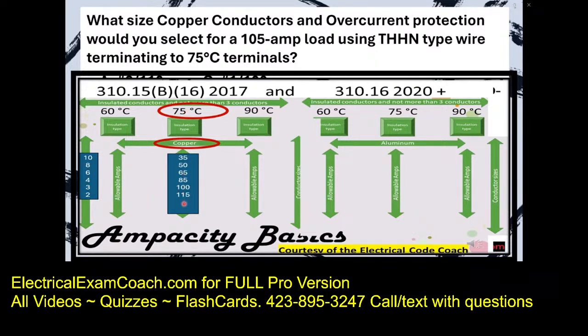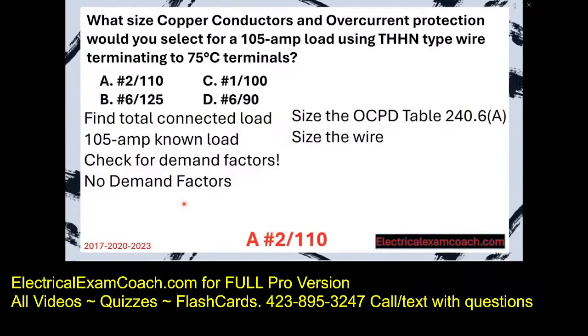And we go down and find a wire that covers the known load, 105 amps, and we're going to end up with a number 2 wire on a 110 amp breaker. Great job!